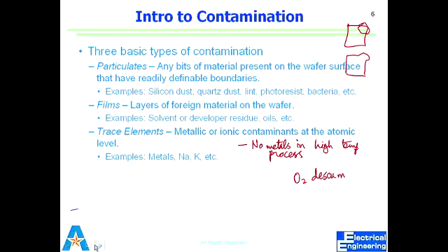What can be the first step of looking at the wafer? Optical microscope. Just put it in and scan the area at low magnification. That can show you many things: layers of foreign materials, the films, the chemicals that might leave some traces behind. Where can oil come from?